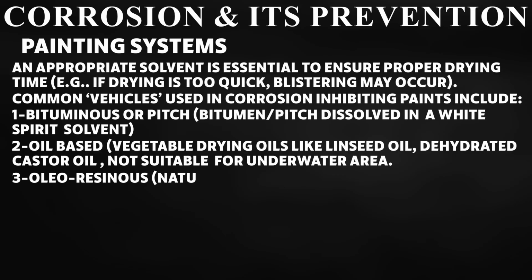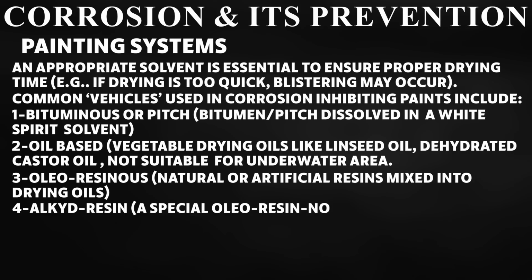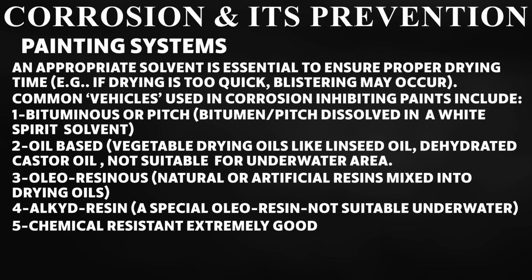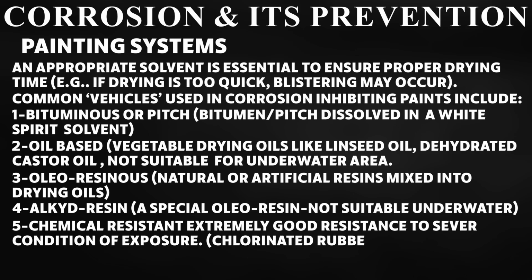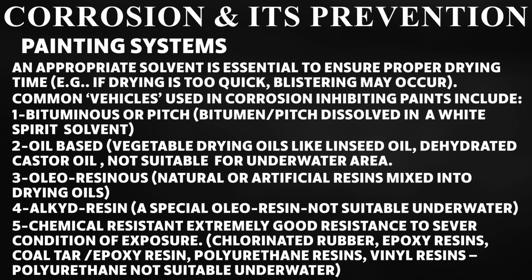3. Oleoresinous, natural or artificial resins mixed into drying oils. 4. Alkyd resin, a special oleoresin, not suitable underwater. 5. Chemical resistant, extremely good resistance to severe conditions of exposure: chlorinated rubber, epoxy resins, coal tar/epoxy resin, polyurethane resins, vinyl resins. Polyurethane is not suitable underwater.